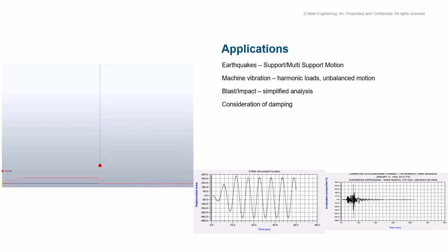And we may want to consider damping during these as well. So that's something that we need to think about when we're running these analyses. If we do have some sort of initial load, for example, is there damping in the structure that is going to basically drown out that oscillation over time so we don't get steady state response during the entire initial loading response?